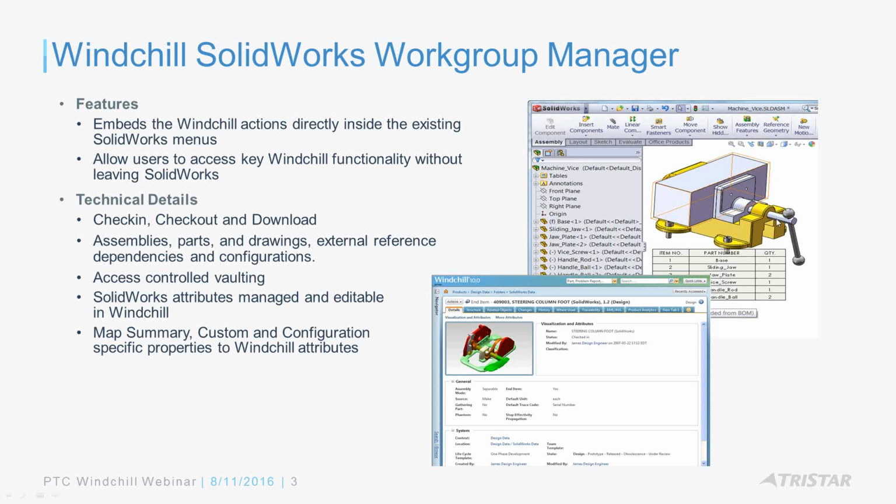On the drawing side, drawings are also managed. You can also manage your drawing templates and attributes within those borders within the drawing, directly tied to the Windchill attribute. So things like a revision, when that changes, no one needs to enter that onto the drawing. That will get automatically updated by Windchill.